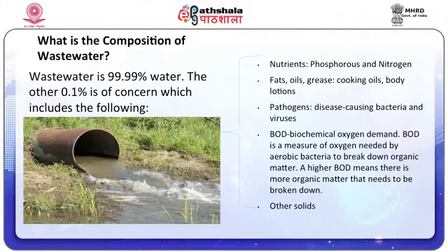What is the composition of wastewater? Wastewater is 99.99% water. The other 0.01% is of concern, which includes the following. First, nutrients: phosphorus and nitrogen. Second, fats, oils, grease like used in cooking oils, body lotions, etc. Third, pathogens: disease causing bacteria and viruses.